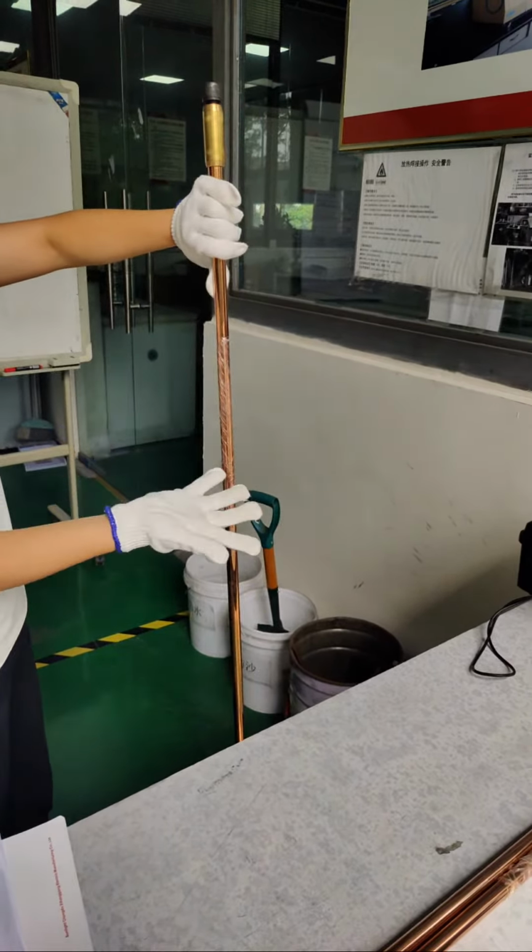And after it is buried underground, over the long term, the earth changes, or an earthquake or something else, the earth will give a force to the electrode. If it's unqualified, then the copper layer will start to peel off or start to have cracks or something else. Not to mention to carry the high current, right? So those are the other two major reasons why we do the bending test. So let's go and check how this works.